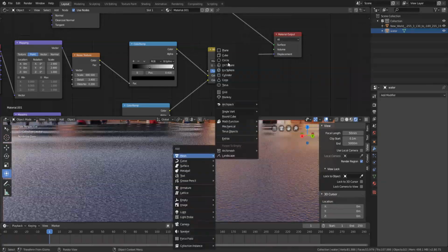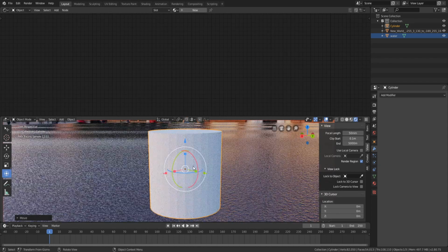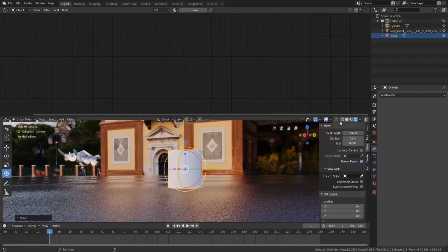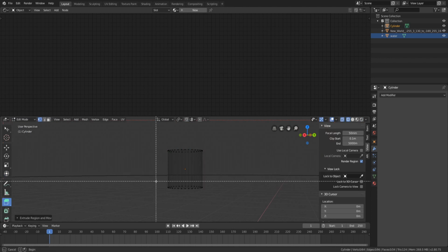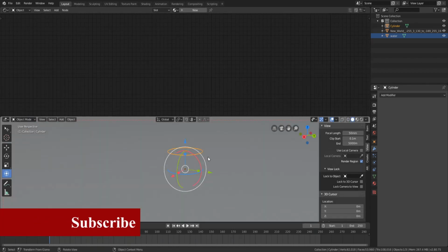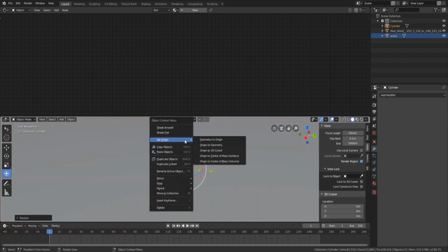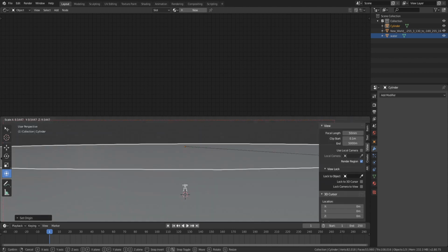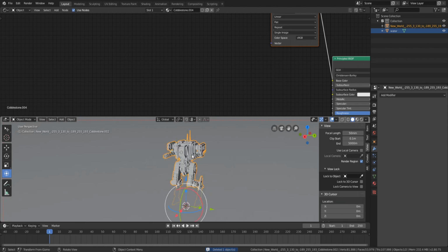So sorry about that. But if you do want to make this disk, just in case you don't know, which I assumed you knew, so sorry, you can go into edit mode and literally just click off and scroll over like that, press delete vertices, and go back into object mode, and there you go. You got yourself a little disk, and then you can scale that up, but then there's that issue. You can right click, and there's set origin to mass surface, and boom, there you go, you got yourself a little disk. And now let's move on.